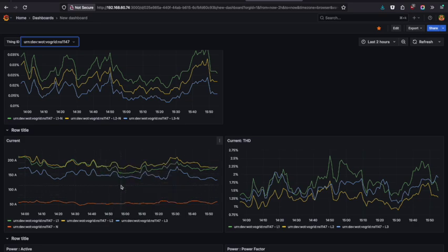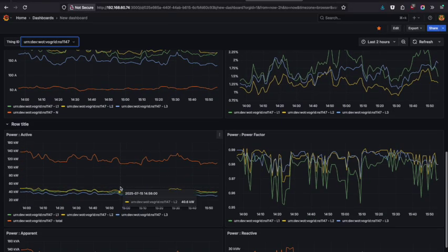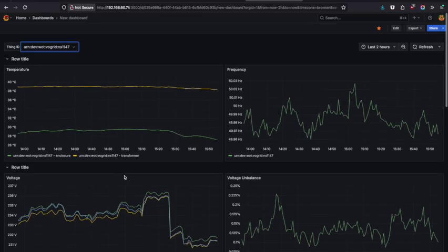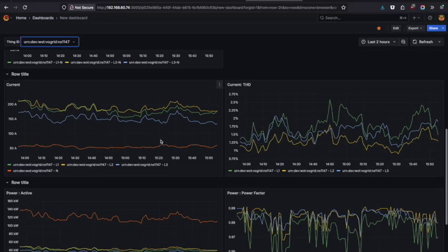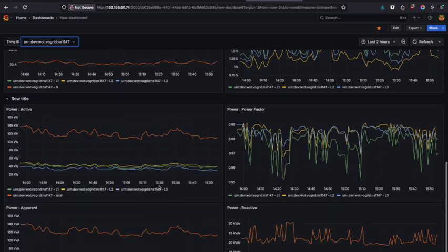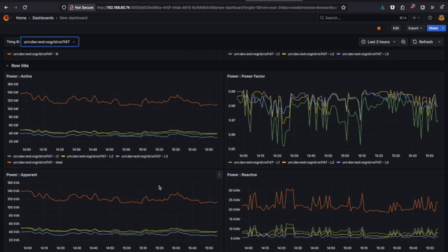This is one of the key parameters that the DSOs use on an operational level to understand what the operational conditions of the transformer look like. We look at the loading of the transformer both on a per phase level and aggregated for the overall transformer. And when a DSO is evaluating the health of the transformer, they're basically looking for correlations between the amount of power that it is being delivered and the thermal loading as it occurs. So the thermal response of a transformer tells them a lot about the health of the transformer, which then helps them make decisions both at an operational level and in terms of planning for replacement or upgrade of transformers.